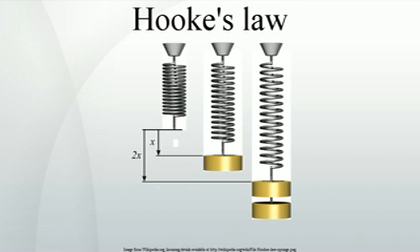The modern theory of elasticity generalizes Hooke's law to say that the strain, deformation, of an elastic object or material is proportional to the stress applied to it. However, since general stresses and strains may have multiple independent components, the proportionality factor may no longer be just a single real number, but rather a linear map, a tensor, that can be represented by a matrix of real numbers.